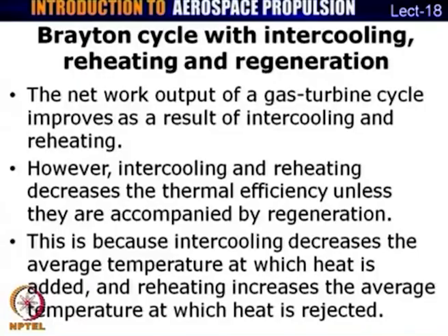Now, primarily what is happening is that during the intercooling process, the average temperature at which heat is added decreases, and reheating basically tends to increase the temperature at which heat is being rejected. And so, that necessarily does not mean that you get an increased thermal efficiency, unless you have regeneration as well applied in the process.